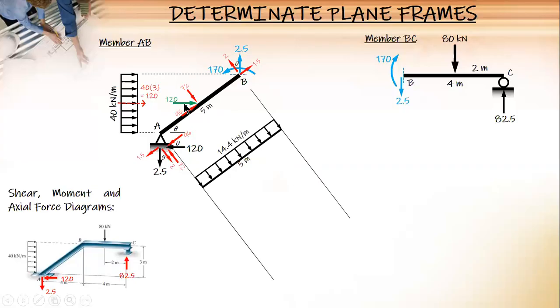And the 96 is the same; it is not concentrated, it is also uniform, since these are components of a uniform load. So 96 divided by 5, 19.2. We draw this uniform load like this, upward 19.2. And then finally, combine 1.5 and 96, we have 97.5.